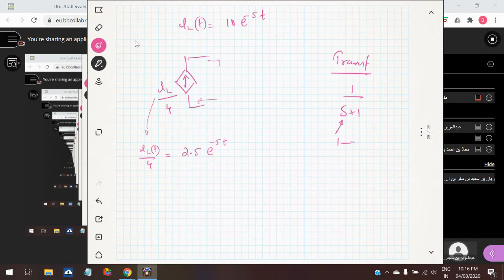That means how many energy storing elements are there? One. When it becomes an RLC circuit, it becomes s square plus something like this. S square means there are 2 energy storing elements. So when you see the transfer function, this is how you can analyze what will be the situation of this circuit, what is the nature of the circuit, how you can relate the physical characteristics of the circuit by using this mathematical equation, the differential equation. This is the meaning of the differential equation.